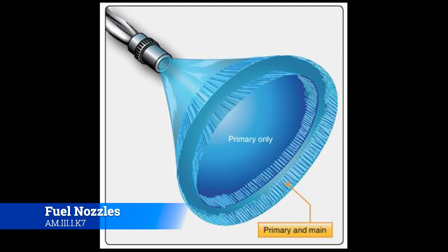Now, spray nozzles have spray patterns, and those patterns will break down into two camps. One is a simplex spray nozzle, which we'll look at here in a second, and then a duplex spray nozzle, or spray pattern. Now, this is a duplex. I could give you a dozen guesses on why it is called that, but you're only going to need one, because there's basically two patterns there.